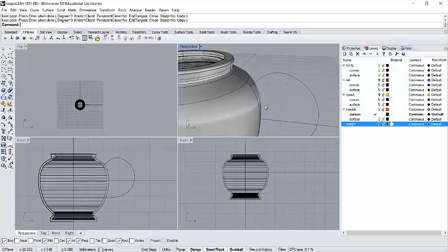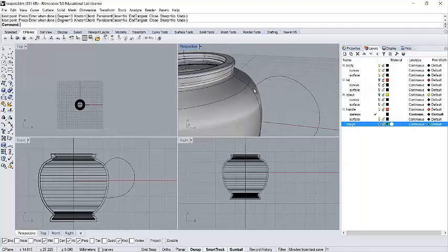So here I want to use some unique C-planes. I'm going to create my own. Now there are a few different ways of doing this, but this is my quick, logical, easy to understand way of doing it for starters. Now I need something on here that's going to emulate the end of my handle.